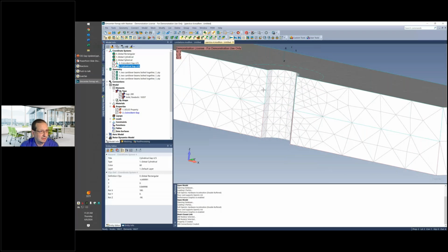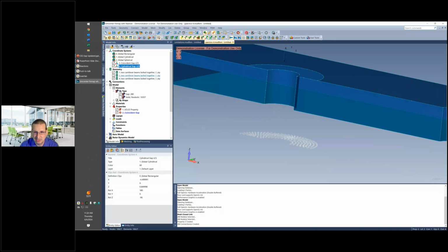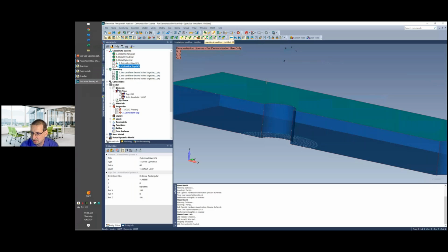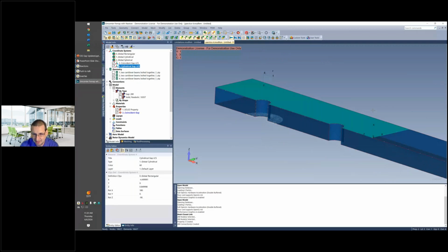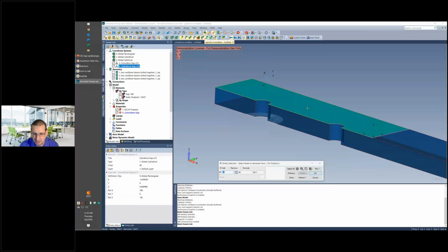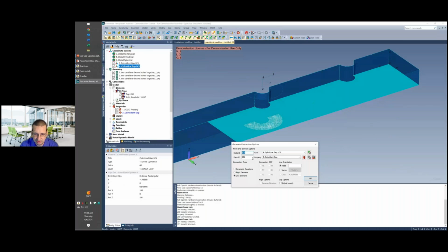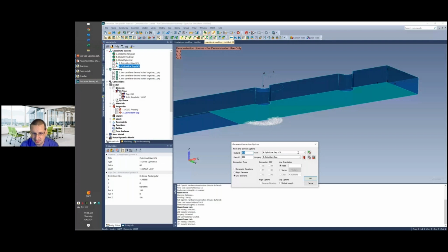I like to leave this off here for this next bit. So now we're going to do between the two plates here. Let's get this orientation or the selected plate right. So again, we're going in that positive X1, so I want the lower plate surface here. Mesh, connect, closest link. Select that surface. Reverse these two. That surface. It's already using our coincident gap that we've defined. That one should be using the coordinate system. Again, I've not had this affect anything in the particular usage cases that I've had so far.